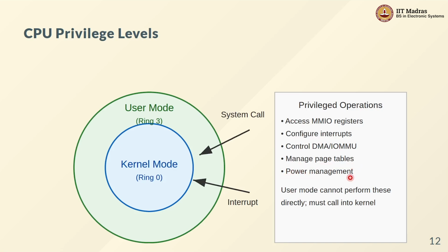For example, you're probably used to the fact that when you close the lid of your laptop, it goes into a sleep mode. How does it do that? The CPU tells all the peripherals to suspend themselves, go into a mode where they can recover from it but are currently not doing anything. And then it puts all devices into an ultra low power mode.